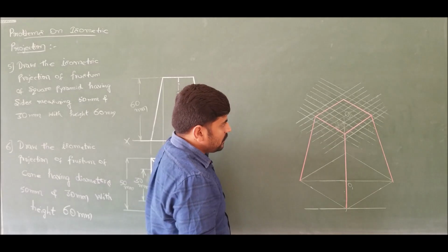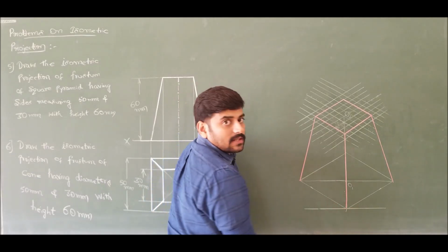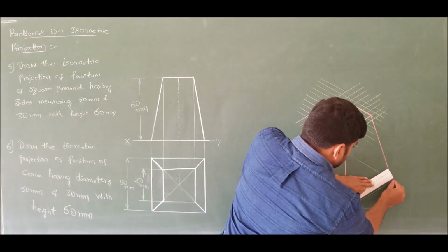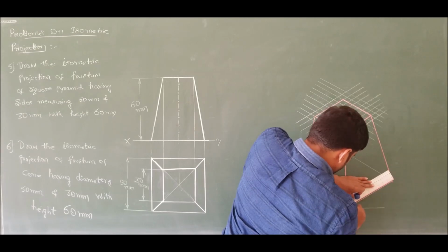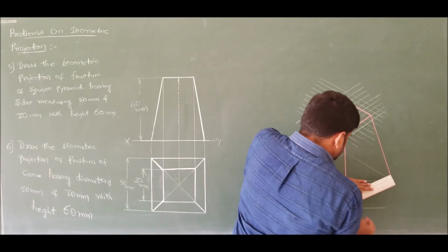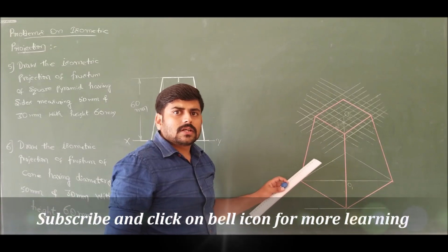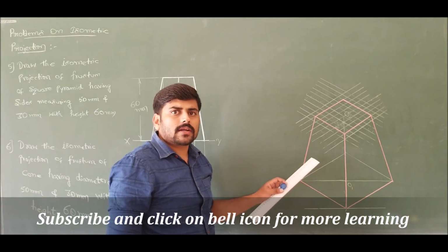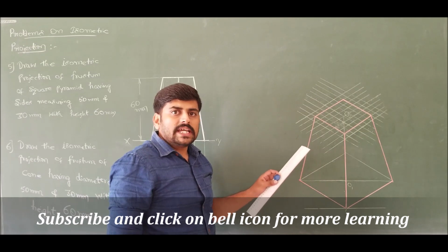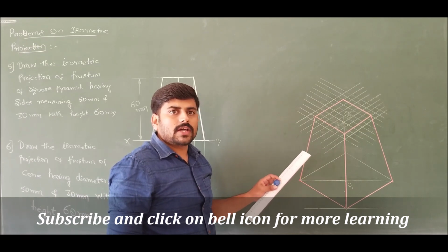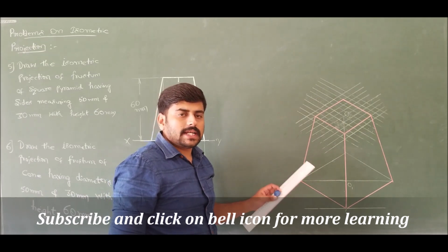And in the bottom face, only these 2 edges are visible. So therefore dark only these 2 bottom face edges. Now don't show any dimensions, don't show any construction lines and also don't show any hidden or invisible lines. So therefore, if I erase them, I'll get.